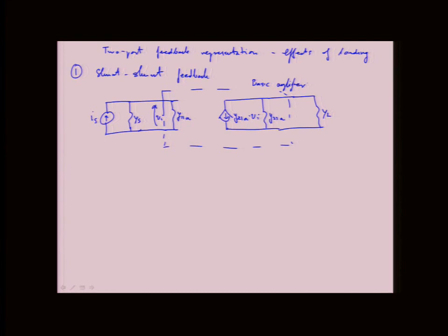And then we have the feedback. Because it's shunt, we have to take the output. So this is going to be VO. Take the output, feed it back. And then here, ideally, in the feedback circuit, we would just measure this voltage, right? So we would present infinite impedance or zero admittance into the feedback network. I'll keep it like this for now. And then on the other side, we try to add current.